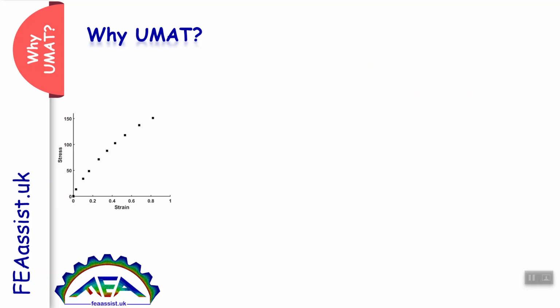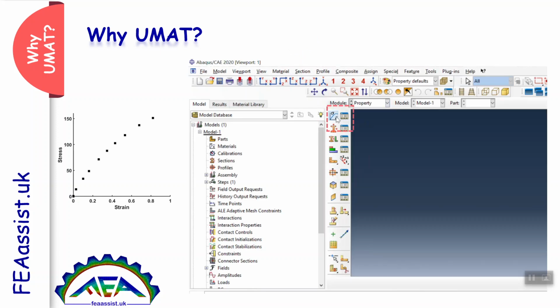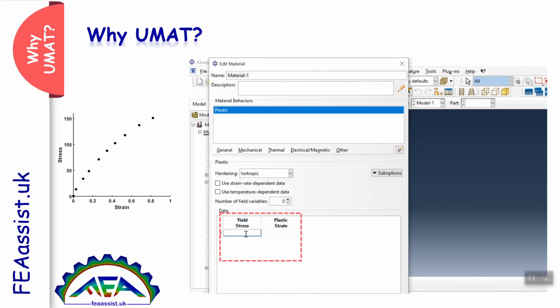The first strategy is that you have some of the points of your stress strain behavior from the lab or from published experiments. You can easily go to Abaqus, to the property, define a new mechanical behavior, plastic behavior, and enter those points like this.